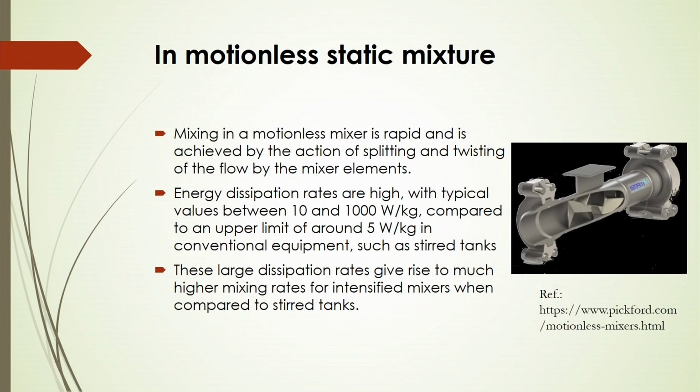Now, let us consider the motionless static mixer. In that case, the phases are mixed in the mixer, and this mixing will be very rapid, and mixing can be achieved by the action of splitting and twisting of the flow by the mixer elements, as shown in the figure here.